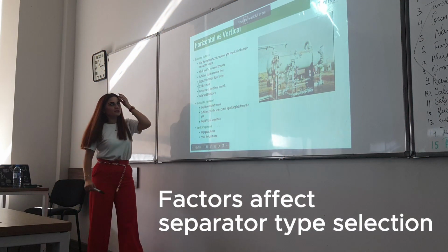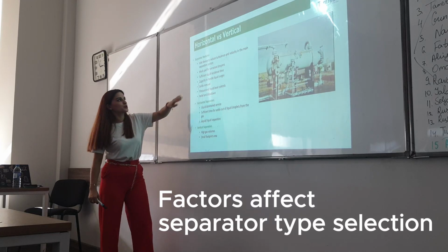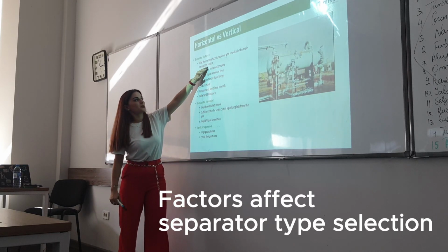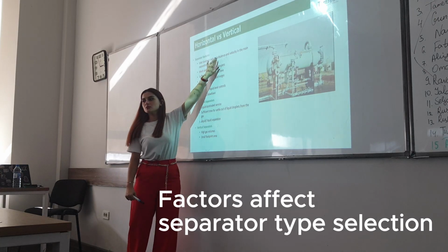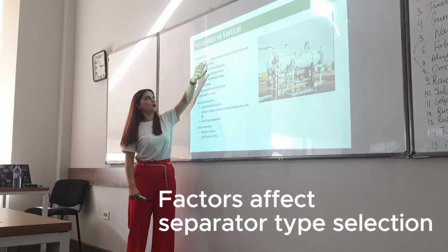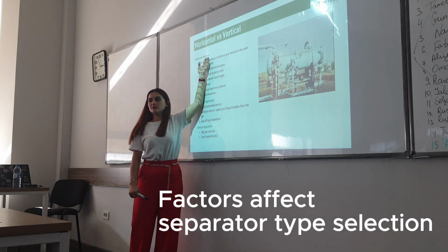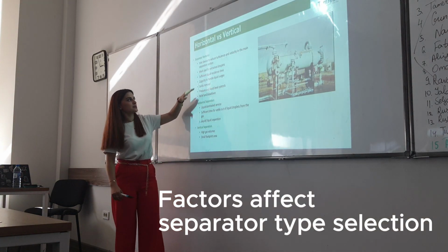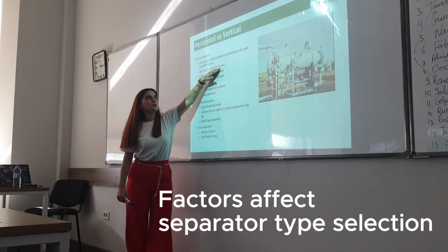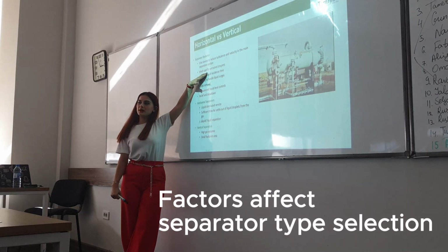Okay. The separator features an inlet device to reduce the turbulence and velocity in the main separation section. How was it called? No, inlet device to reduce. Inlet diverter distributor, yes. Mesh pad for entrained droplets. Mesh pad, why we are using mesh pad?